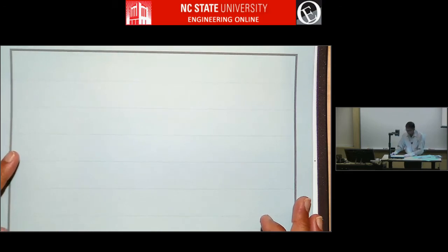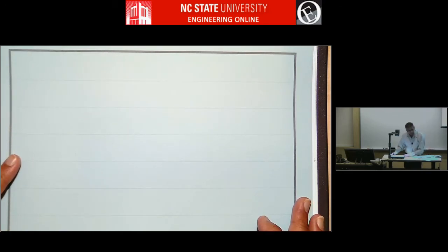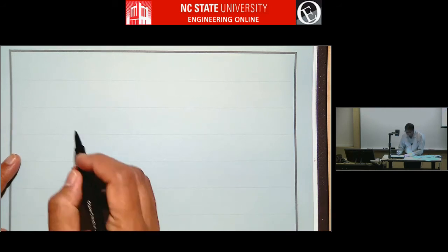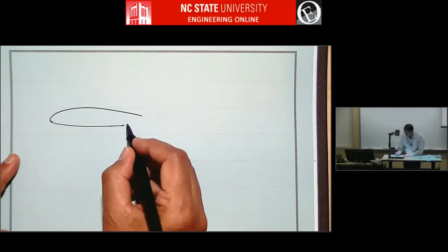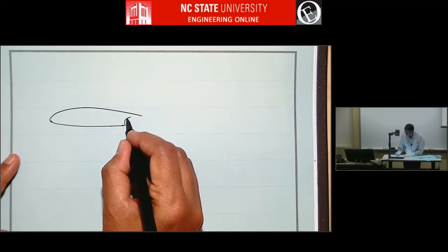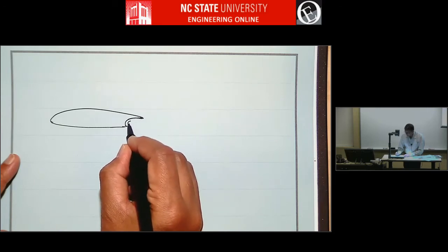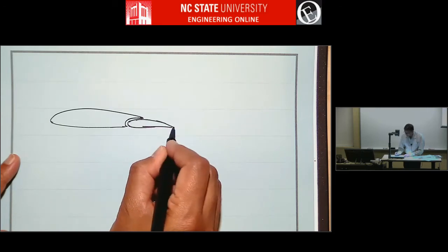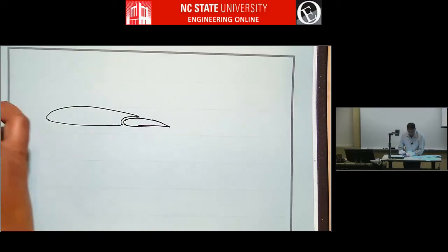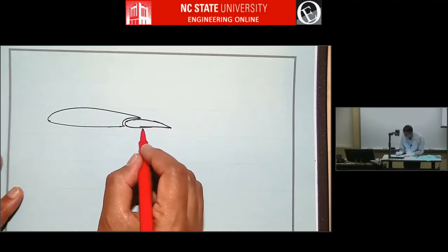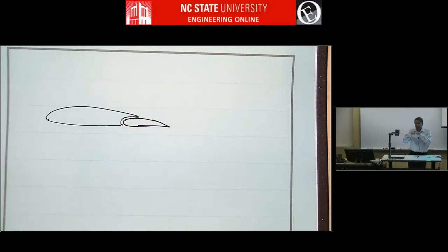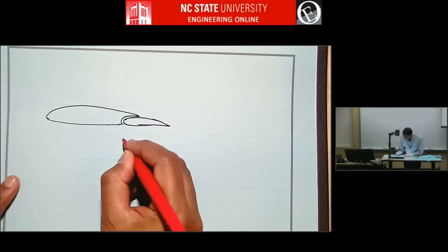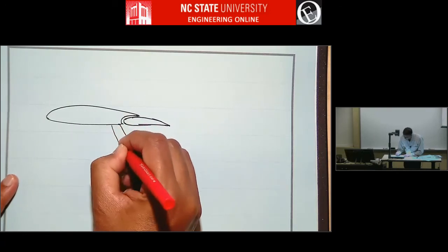Well, we had a three-part airfoil, so we had a slot and then a flap, and when it was in full landing position, it was longer. So there are airfoils where the flap will actually nest. This is how the airfoil will be, and then when you deflect the flap, it will not only deflect downward, it won't just pivot. It will pivot and come out, or the pivot might be outside. For example, if the pivot point is here, you could have a mechanism like a flange